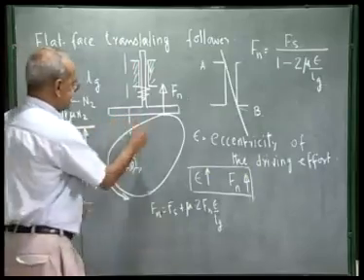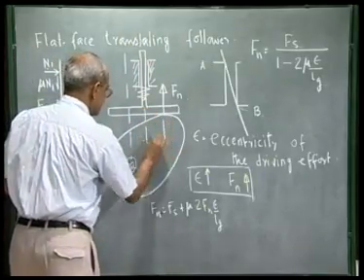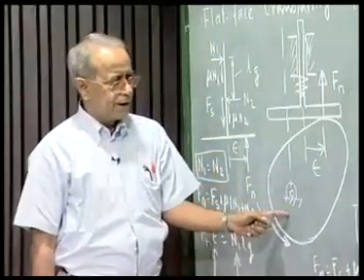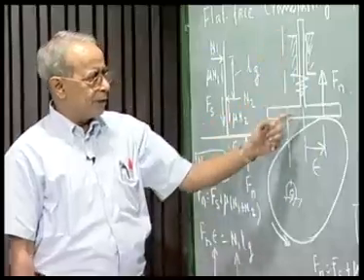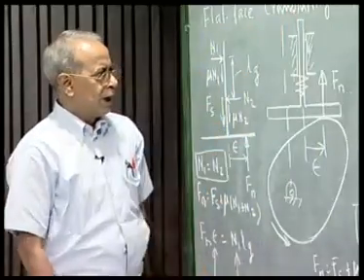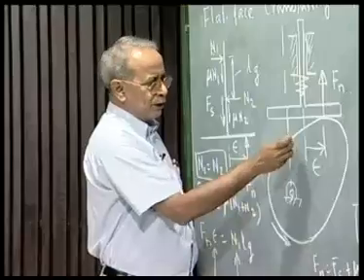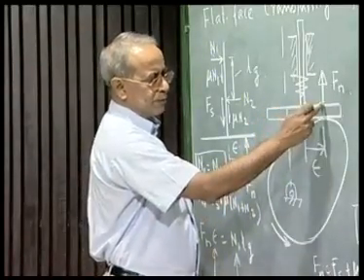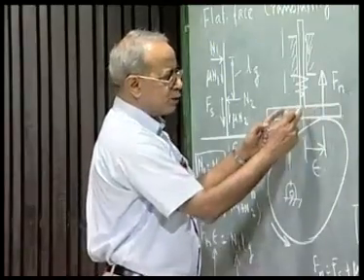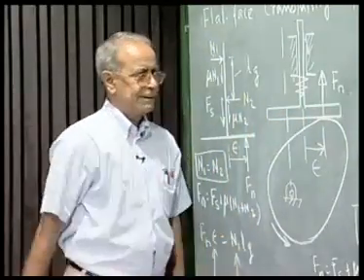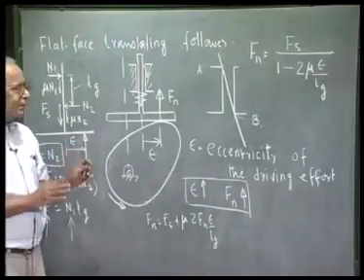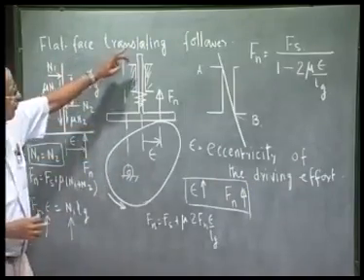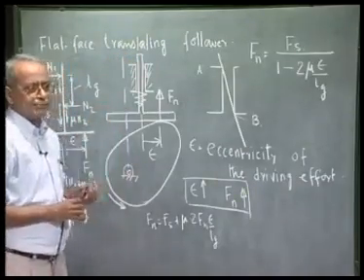So more is the eccentricity, that is this distance, more driving force is necessary. And this is more critical while going up, because you have to overcome the spring force. And this offset, as we shall see later, obviously decreases the eccentricity. Had this axis been here, the eccentricity would have been so much, and now the eccentricity has been reduced by this amount of offset. So this explains the importance of the free running of the follower in the cam follower system.